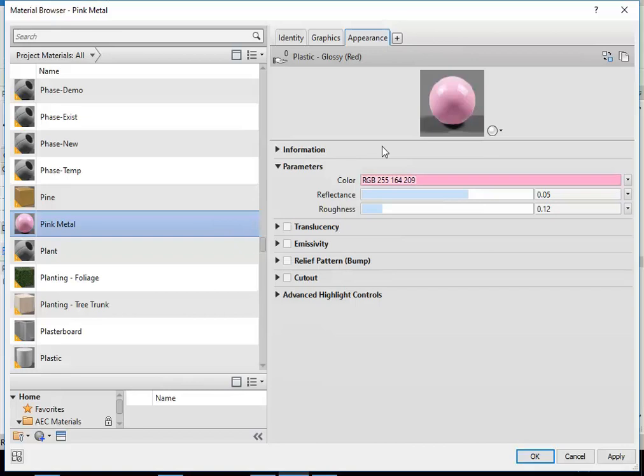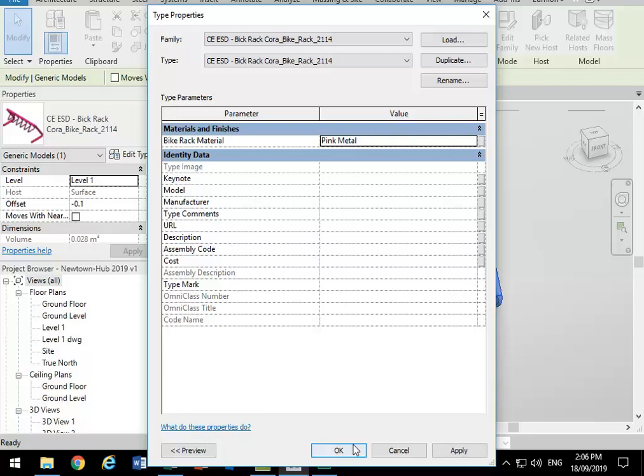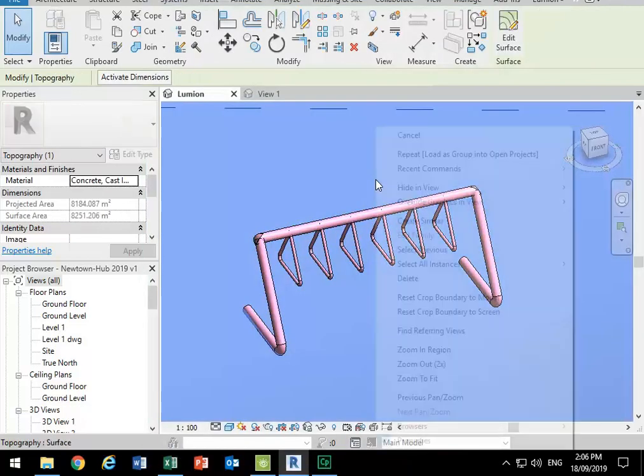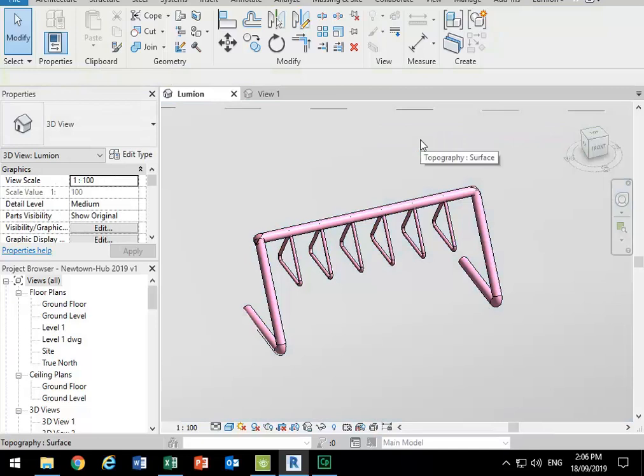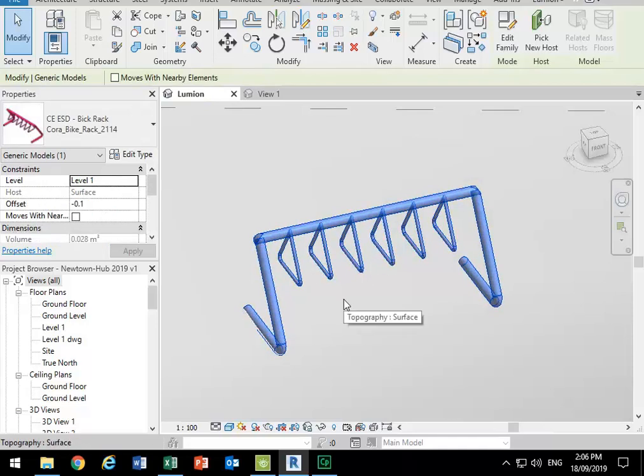So is it essential for families we make ourselves? It's mostly for downloaded families. If you make them yourselves, then you should set up your own parameters for everything you make so you can change the materials. Otherwise, you'll have to go back to the family each time to work out what material they're using. So until you can set parameters for materials, you won't be able to effectively change the materials when you're in a project file. And I know it seems like extra work, but this is the main difference between programs like SketchUp and programs like Revit. It's set up to manage large groups of objects.